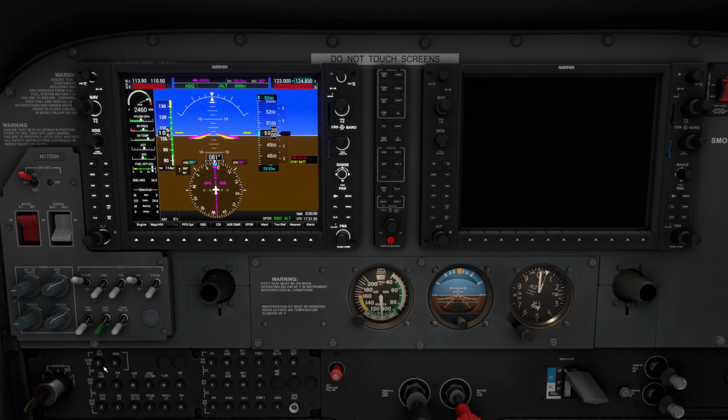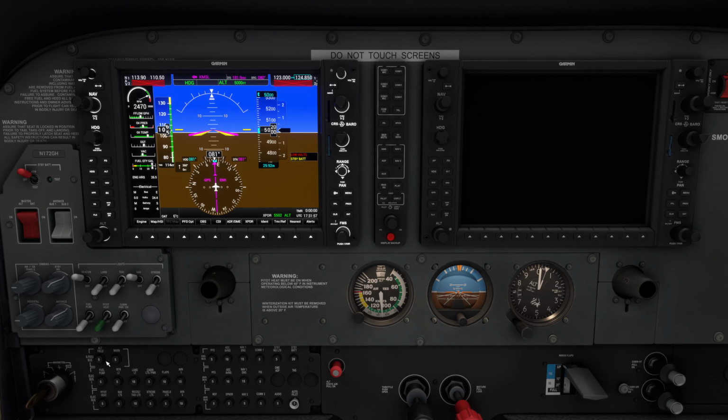And you can tell what's powered on what buses in the 172 by looking at these circuit breakers down here. The only things we have are the crossfeed bus and the essential bus. The essential bus has the primary flight display, the ADC and the AHRS, so the air data computer and AHRS, so we're still getting airspeed and altitude, and heading information and attitude information. We have COM1, we have NAV1, we have the engine instruments, we have the standby instrument indicator lights, so those will continue to be illuminated.